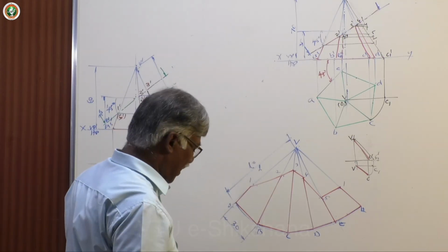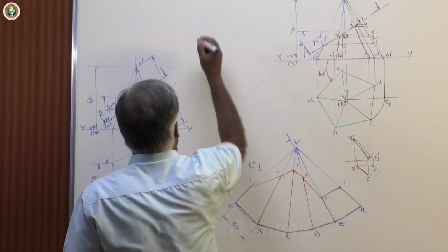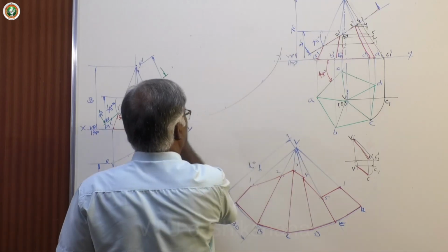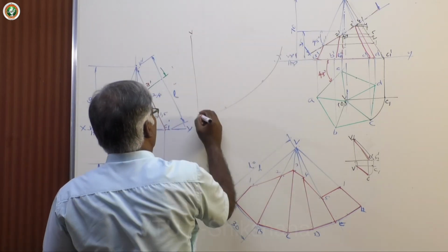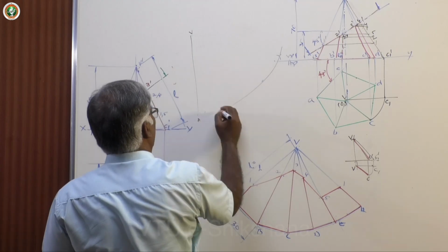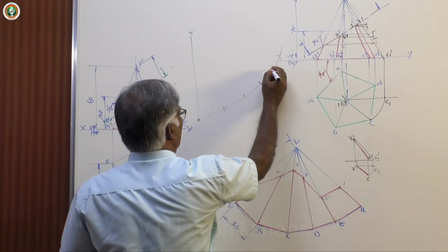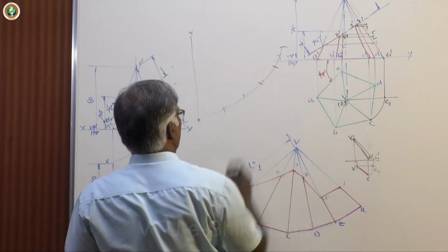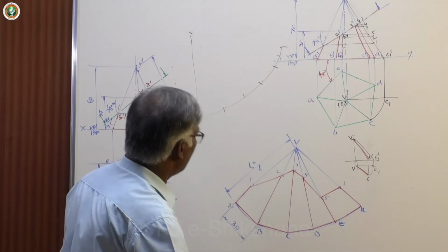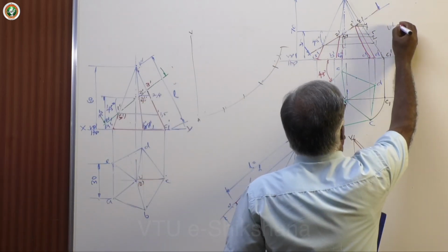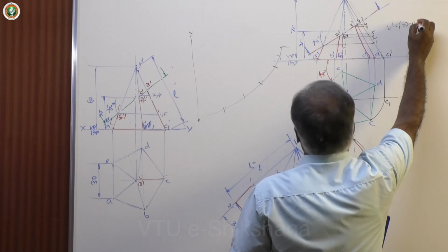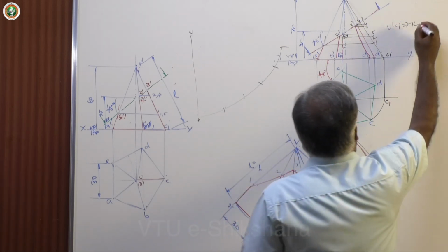Assume that I have a space here and then mark here 5 points. Then this is VA, then VB, VC, VD, VA again. Join them in order. What is the distance? True length. V dash C dash is true length here also. So that is equal to L.